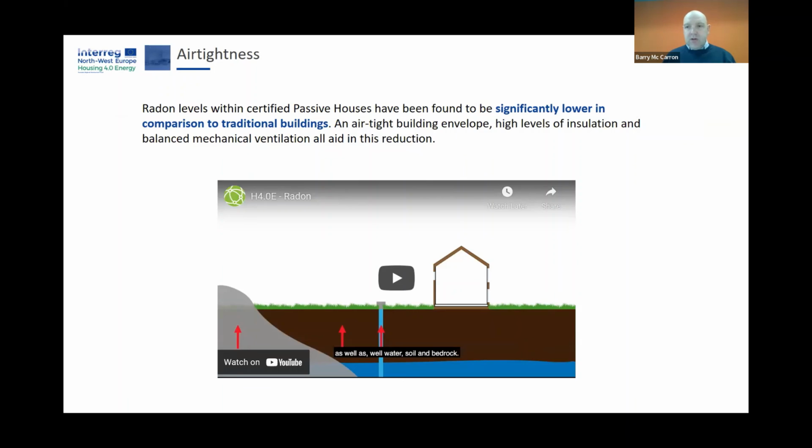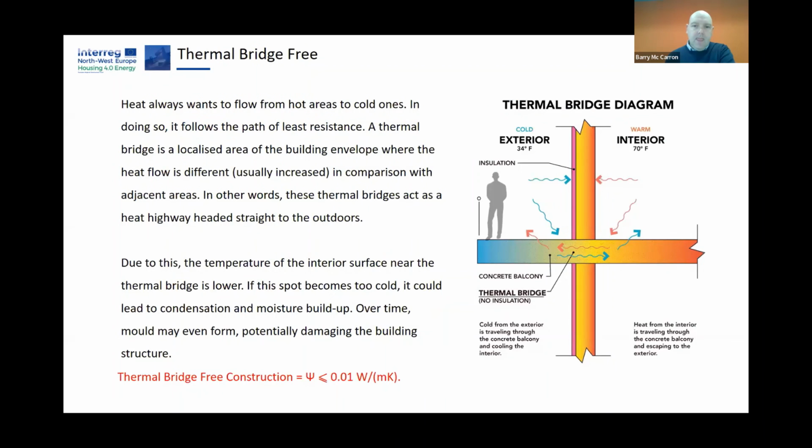My own research for the PhD was in radon. So again, I was examining over 100 passive house buildings here in Ireland to see was radon better or worse in them compared to normal building stock, and was pleasantly surprised by the results. So you're talking about a 50% reduction in the presence of radon in one of these certified passive house buildings or a low energy home. And again, this is just reiterating the thermal bridge phenomenon that we talked about earlier in this slide.